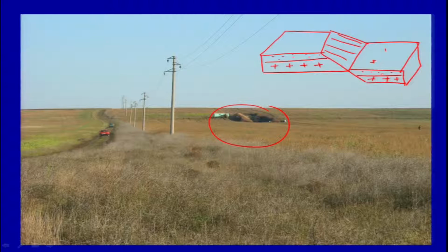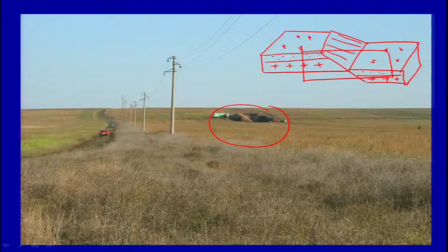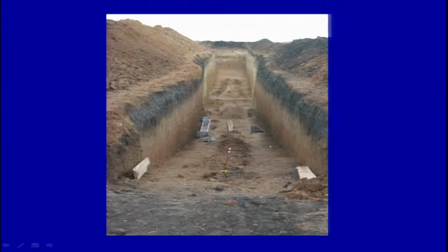So this is your surface. So to see this part here, they opened up a trench somewhere at the base of the scarp, and this is what has been shown here. Okay, fine. And this is what they got. Okay, so this is a scarp here, this is a footwall, and this side is the hanging wall. The fault runs somewhere here. Okay.